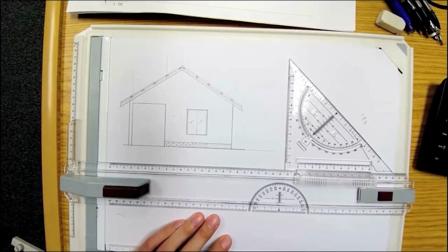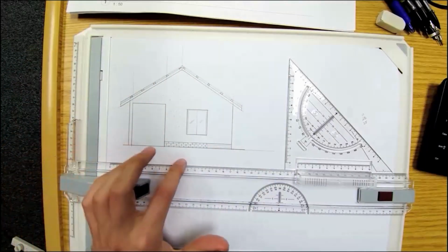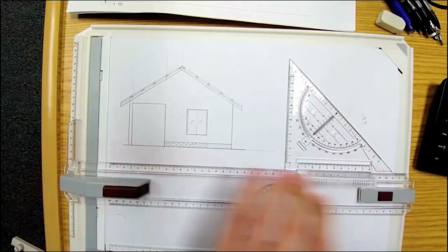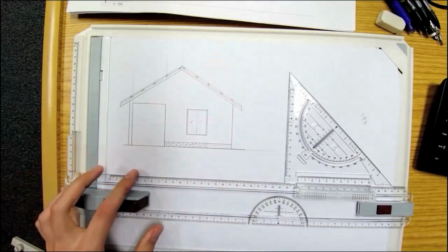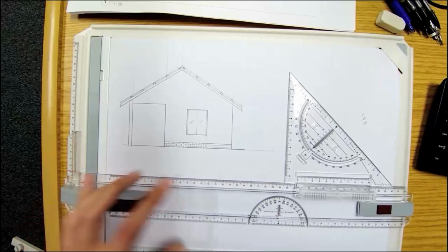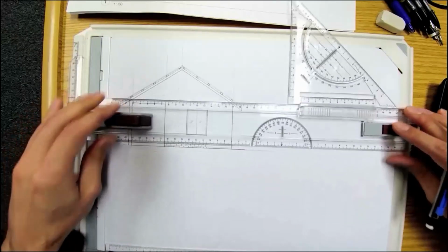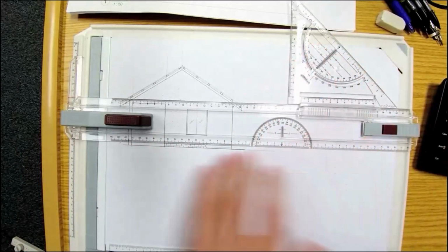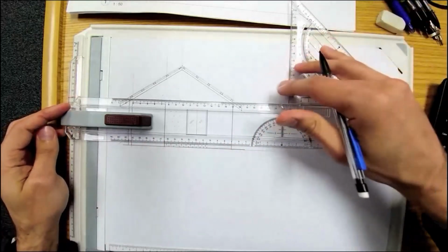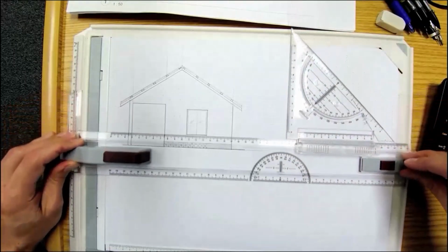And the next step is adding the dimensions and the titles here, not the title block. Adding the dimensions and the title here, and drawing the second elevation right here, and leave this right side of the paper blank, empty for now, because we're going to need this top right region here to draw the wall detail, right?